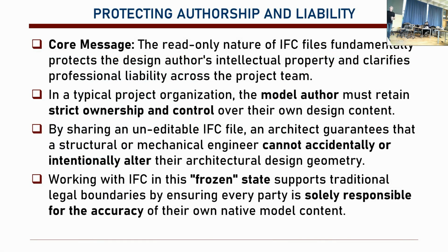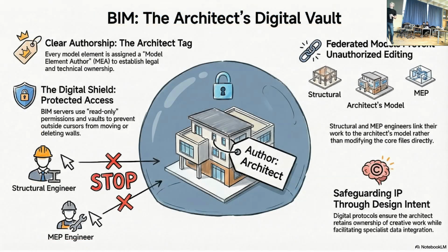Okay? Frozen state basically gives you total control of your native model. The Revit model is yours. And you have different versions of your Revit model. It's yours. Okay? You just give your Revit model as an IFC file to the engineer. They work on it. And if there's something wrong, they report back. Okay? So, yeah, it's a shield.